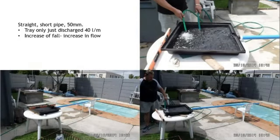Right, now we put a short 50 mil PVC pipe on at a reasonable fall. The tray, you can see, has got a fall on it. The pipe has got a slight fall on it. It's a straight pipe, straight out. The back of the tray there is empty-ish. The front of the tray being lower, it's discharging. There's nothing running back over the tray, but it's not what I would call comfortable.